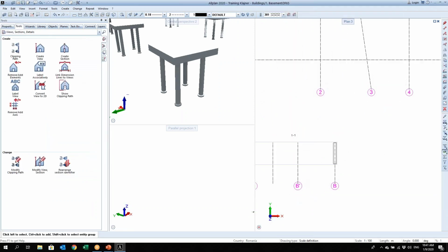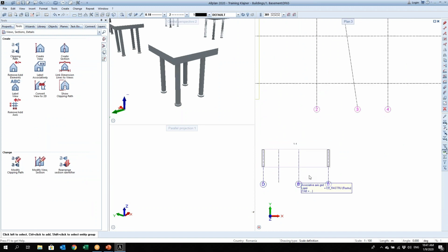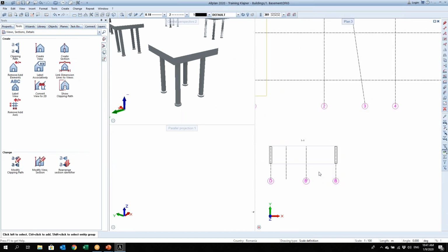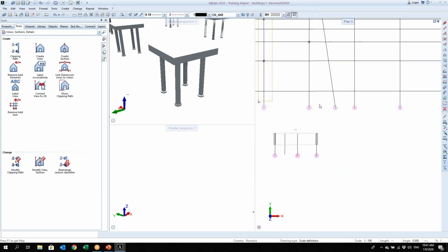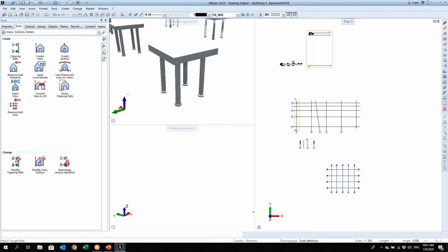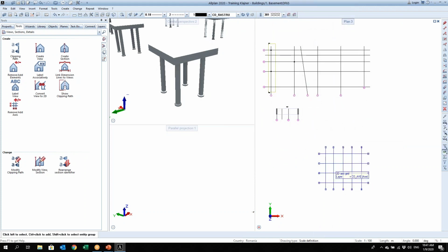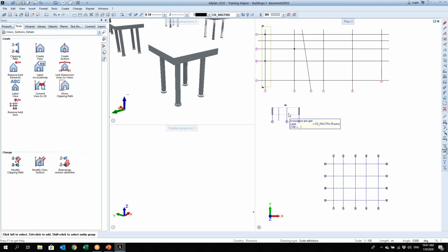Another innovative thing is that before you couldn't do this with the classical grid system, because they were looking for architectural elements. So if you wanted on the elevations to lower the axis, you could only do it if you had architectural walls or columns. Now, this new grid system forces you a bit to work with the unified views and section system. So this is how they go around.